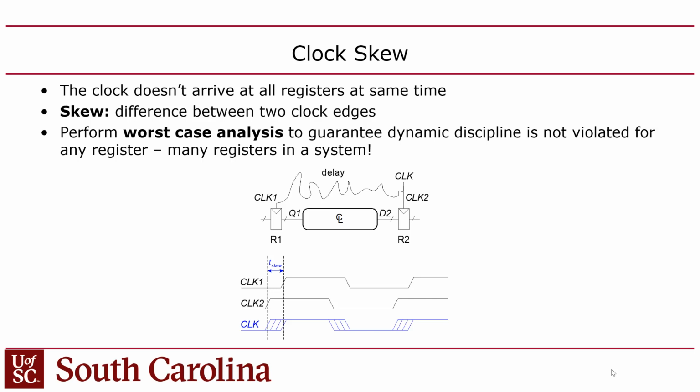But from the multiplier, which is an analog circuit, a phase lock loop, out to the rest of the chip, you have this thing called clock skew, which basically means that there's going to be a different version of the clock at every point on the chip, in terms of timing, right? They all look like a clock. They're all 50% duty cycle, but shifted, right? That's called clock skew. And so you have to incorporate the clock skew into this timing constraint as well. So generally, the way this works is you assume a maximum clock skew, and then you do your timing calculations based on the maximum clock skew, and you build that into your calculations.